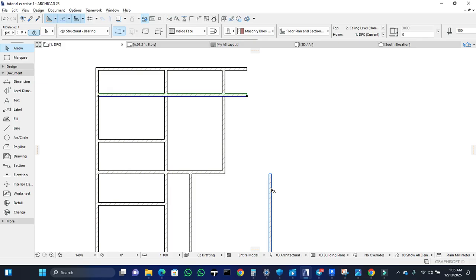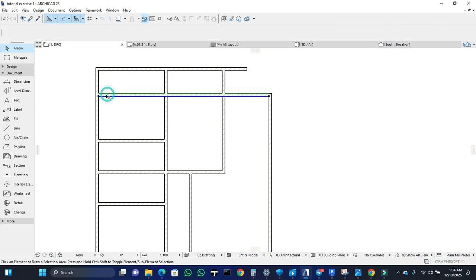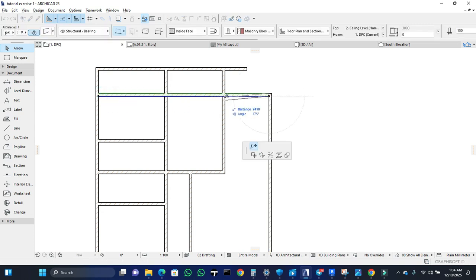As soon as you hold your control key, anything you click on will trim. So that's a shortcut I just taught you. Now we can make this little space the exit veranda. So let's just select two perpendicular walls and intersect them.